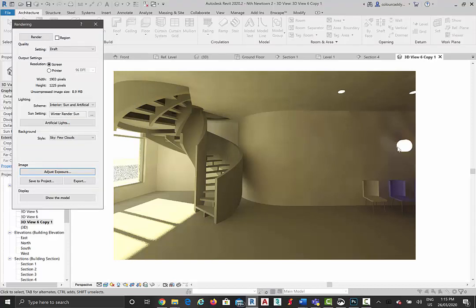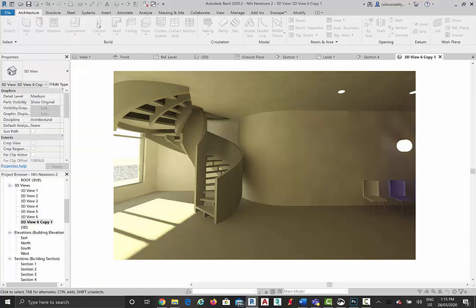So then the final thing I was going to say is you can still get scenes to work with sunlight and artificial, but the main workaround people use is to make the artificial lights far, far brighter than they would be normally. And I mean about 10 times brighter than they would be normally. Which I know might be surprising, but that's just the way it is with the engine that you have with Revit.